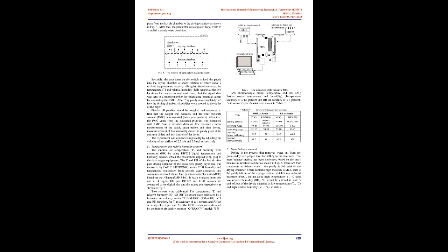See experimental setup and drying process. In a cross-flow dryer experiment, the process started from a dryer setup. Fig. 2 shows the flow chart of the experimental procedure of the paddy drying process. Firstly, the moisture of the fresh paddy was measured by a moisture detector kit, Riceter F512 model, compression type with an accuracy of 0.5%, for an initial moisture content range of 20-21% wet basis, and each experiment was performed in 3 replications.